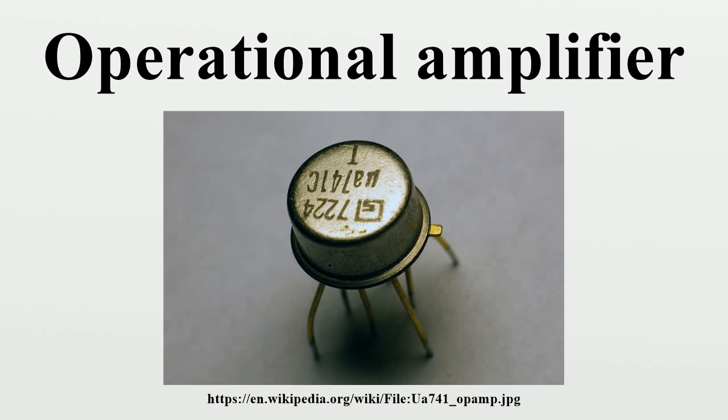Operation. The amplifier's differential inputs consist of a non-inverting input with voltage V+ and an inverting input with voltage V-. Ideally, the op-amp amplifies only the difference in voltage between the two, which is called the differential input voltage. The output voltage of the op-amp V_out is given by the equation, where A_OL is the open-loop gain of the amplifier. Open-loop amplifier. The magnitude of A_OL is typically very large, 100,000 or more for integrated circuit op-amps, and therefore